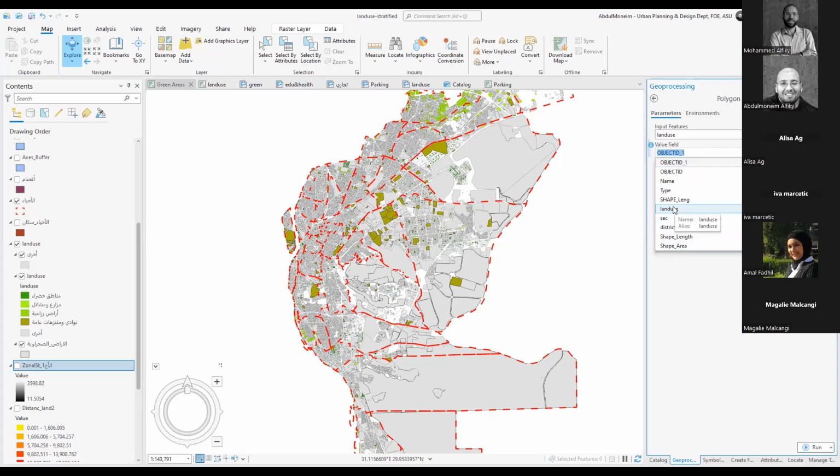Of course, I have a problem with the land use here because it's written text. It's not coded. It's not 1, 2, 3 with a code in a domain or somewhere, but actually written text. So I'm not going to use it, but the correct way is actually having the land use in coded format, and I would simply choose it. And whatever the system creates, every pixel will get a value based on its actual land use.